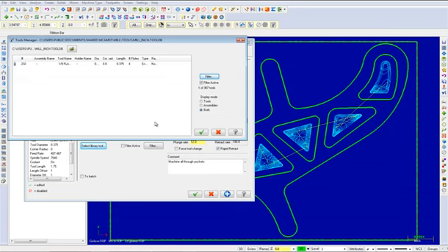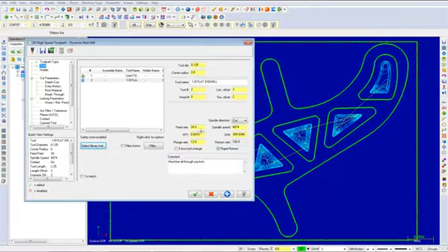In the Tool Selection dialog box, you should now only see a 1/8 flat end mill. Choose this tool and select the OK button. Your tool will appear as shown. Input the following comment: Dynamic rest mill all through pockets. Once the comment has been entered, select the cut parameters.